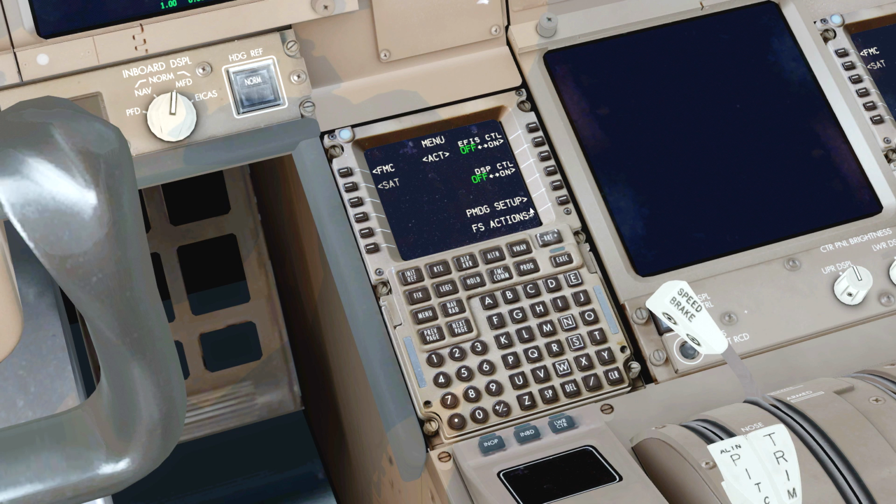So what we want to do next is go to the FMC. Right now we already set the inertial reference position, as I just showed you when we aligned the ADIRU, and we're now going to just continue ahead. The FMC is pretty straightforward to use on the Boeing. We'll just go to the next page, which is our route page. Now, if you're used to the 737, this is going to be a little bit different.